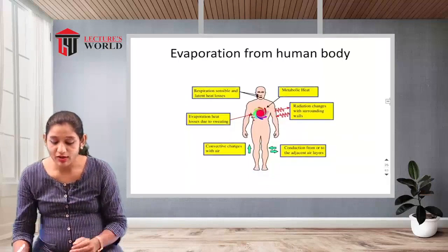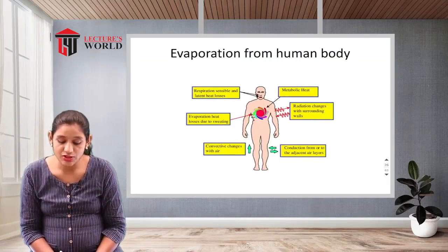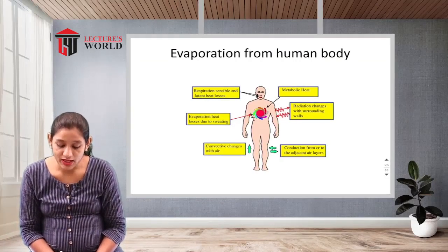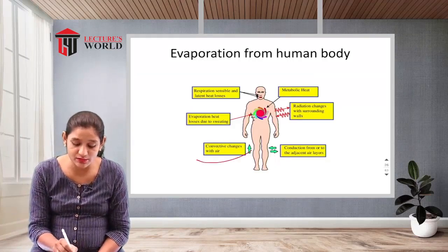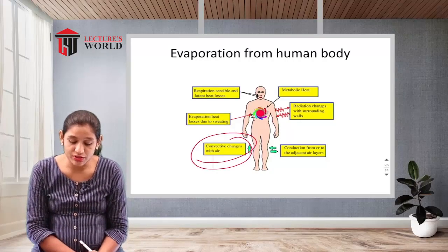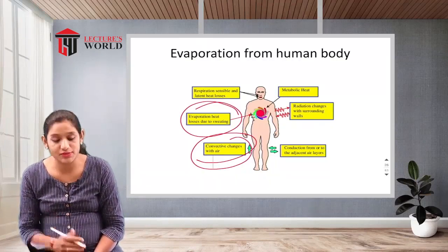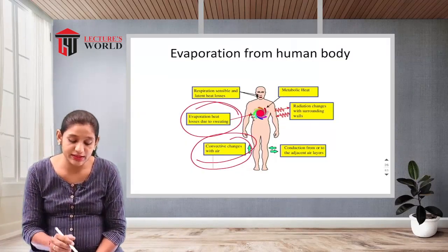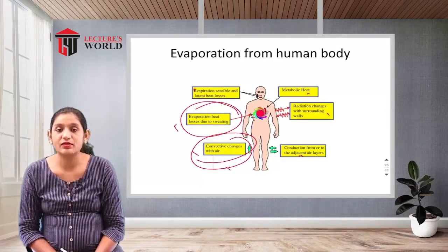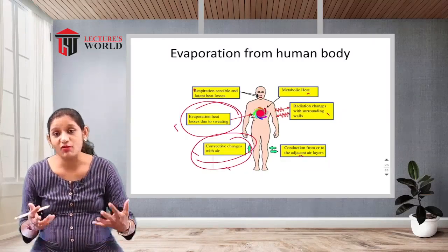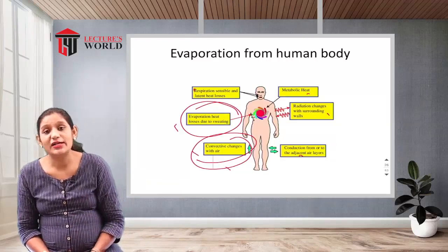Next one. Heat exchange in the human body includes metabolic heat, radiation exchange with surrounding walls, conduction from or to the adjacent air layer, convection exchange with the air, and evaporative heat losses due to sweating and excessive respiration, by sensible and latent heat losses. Evaporation means loss of water molecules from our body.